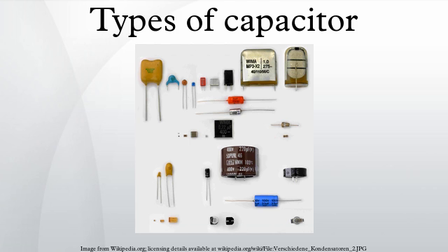In IEC EN 60384-1 the allowed operating voltage is called rated voltage, or nominal voltage. The rated voltage is the maximum DC voltage or peak pulse voltage that may be applied continuously at any temperature within the rated temperature range. The voltage proof of nearly all capacitors decreases with increasing temperature. For some applications it is important to use a higher temperature range. Lowering the voltage applied at a higher temperature maintains safety margins.